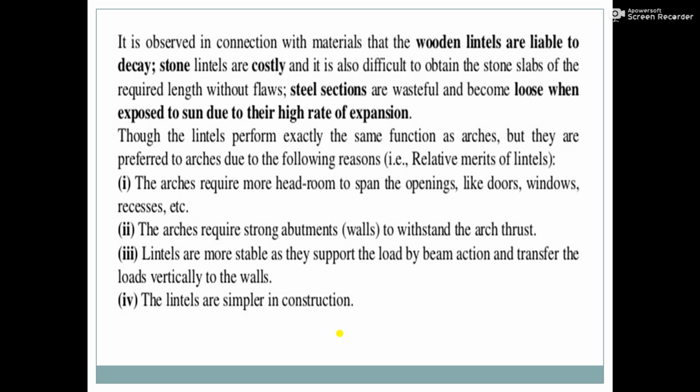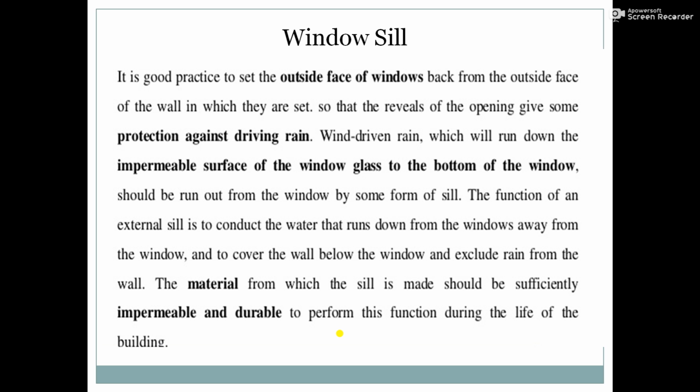So it is observed in connection with the materials that the wooden lintels are liable to decay. The stone lintels are costly and it is also difficult to obtain the stone slabs of the required length without flaws. The steel sections are wasteful and become loose when exposed to the sun due to their high rate of expansion. So because of all these things, the reinforced cement concrete lintels are the best suited for use as lintels in RCC structures.